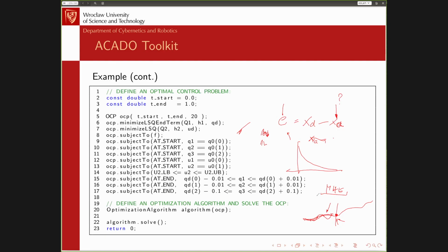So the moving horizon estimator is one of the methods which allows you to do this, and it does it in an optimal way. So it uses model information and it uses measurements. You can measure different things. You don't need to directly measure what you need for your state, right? And you can also get the state. So this is something very interesting. I think it's worth knowing that such algorithms exist. Okay, so this is it from my side.